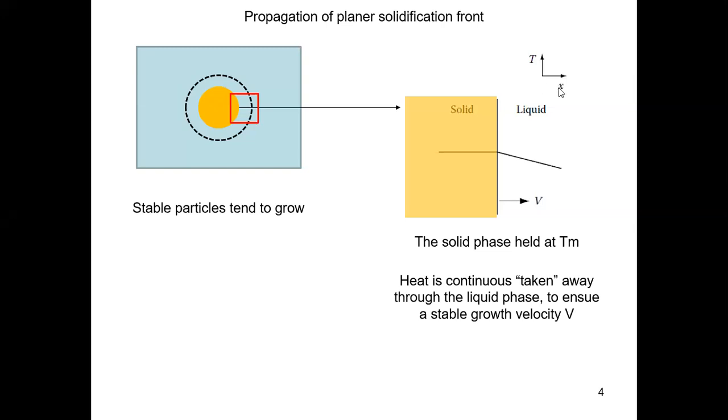So basically, we're establishing a coordinate system. We imagine that we have an axis along the horizontal direction right here. This is my x-axis. We can use this axis to denote the location of my solidification front. And in this particular case, the y-axis simply gives us the temperature. In the solid, we have a uniform temperature distribution, equal to the melting temperature. And in the liquid, we have a decrease of the temperature, because we impose supercooling. That's basically the setup. Any questions on this one?